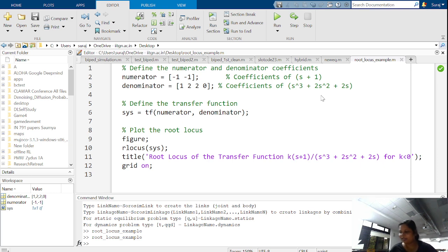Okay. So in the beginning, when we had started this question, this root locus, what we had said was that as we keep increasing k, we would essentially see how our closed loop pole varies. Now you see, k is already less than 0 in this case. After the condition of k less than 0, whatever you do, you see that this pole will terminate